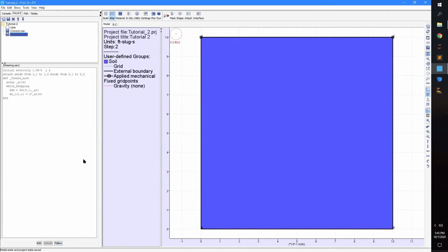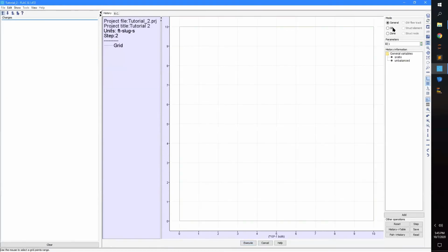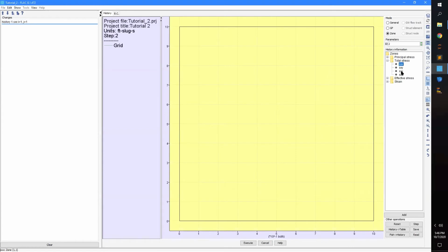All right, so we have this. I'll show you how we're going to use this later on, but now we're going to add some histories. So click Edit, go to Utility and History, and now we're going to add some histories. So what do we want? We want to get a bunch of histories for stresses, and I'm going to plot a few. So let's go to total stresses. So let's do the horizontal normal stress, the vertical normal stress. Oh, I need to do that, and then I click here, there, and then here, and then there.